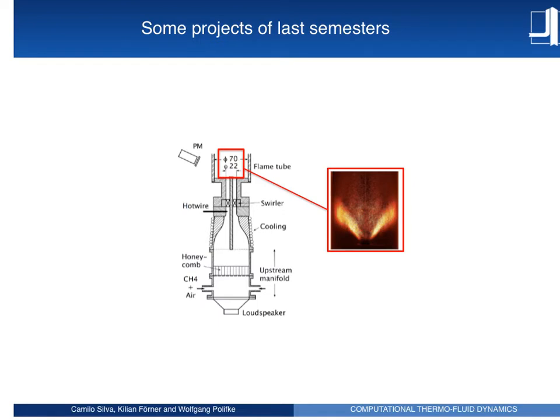And the thing is that the flame is moving, and this flame surface area is changing, producing some acoustic waves. And these acoustic waves can actually go outwards from the domain, and then they come back reflected by some walls or some surfaces in the surroundings, and then you will have a resonance inside the combustion chamber, and that can cause failure in engines, for example gas turbines in aircraft, or the typical example of rockets some decades ago.